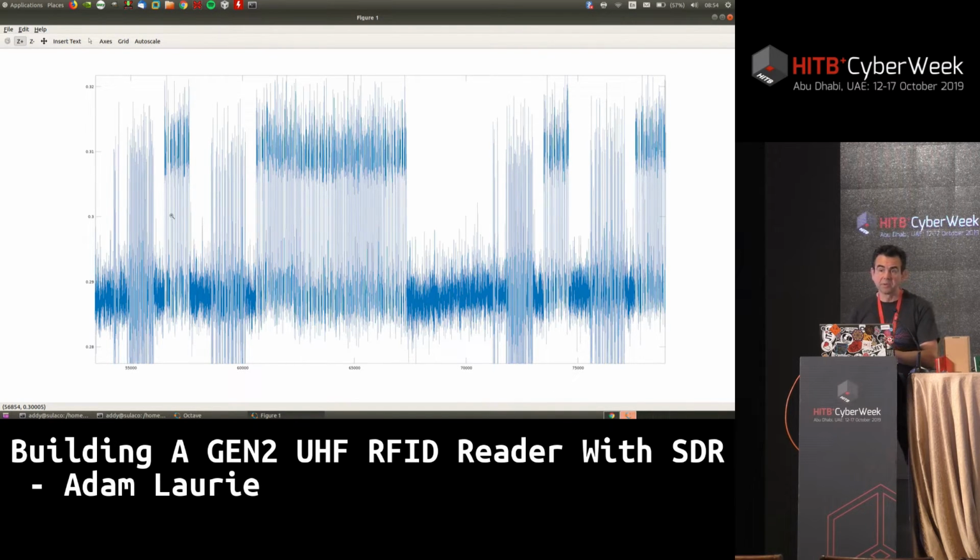really critical time period. And the reason that I've looked at this project, and there's a lot of forks of it, and you can see people clearly trying to get this working. And it looks like from the additions they're making to the code, they went down the same path I did, which was, well, I've got the radio working and I can see the tag sending me this random number, but it never responds when I send the command. So maybe I'm getting the random number wrong, or I'm filtering wrong. So I started changing the filters to band pass or low pass, whatever, trying to get a better signal. And I never got a response.